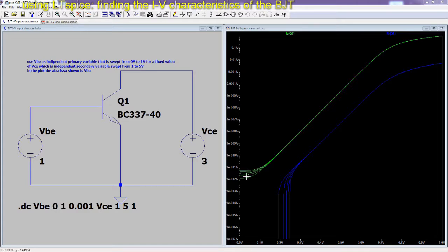What we should note here is that really for the values of VBE when the BE junction starts to conduct some current, which is basically, you can see, above 0.3 volts, effectively the value of VC is not so important. All the curves here are one over the other, both for IB and for IC.